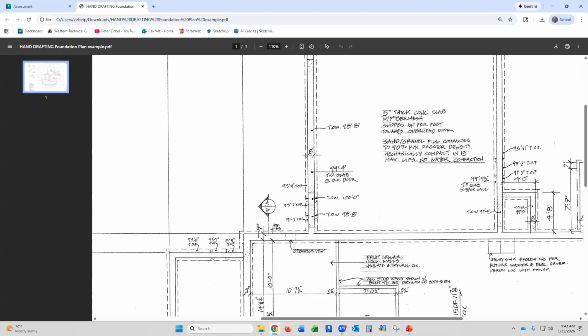You can slope it to an interior floor drain in the middle of your garage. How many of you have an interior floor drain in the middle of your garage? Not many, it's very rare, because the problem is they dry out and then the stink comes up into your garage and all this other stuff. So most people's garage slopes to the overhead door.